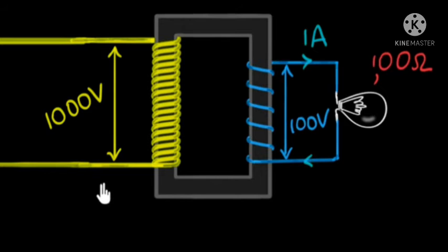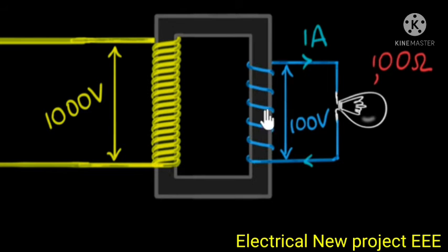But now the question that I want to ask you is, how much current do you think will flow here? Now that's an interesting question, because this is a different circuit altogether. How do we figure that out? Well, we can use one of the basic principles of physics, energy conservation. We can say that, look, in a transformer, there is electrical energy being transferred from here to here. So whatever energy is lost by the charges in this circuit must be exactly gained by the charges in this circuit, if this is an ideal transformer where there is no energy loss.